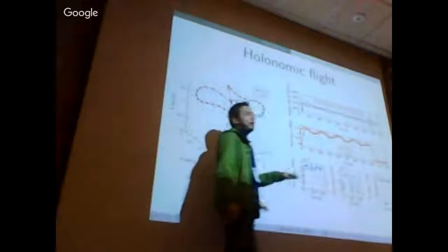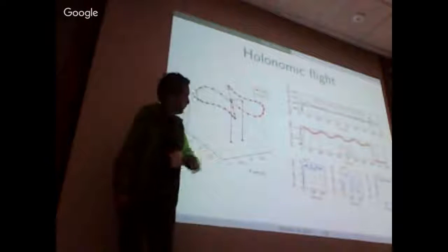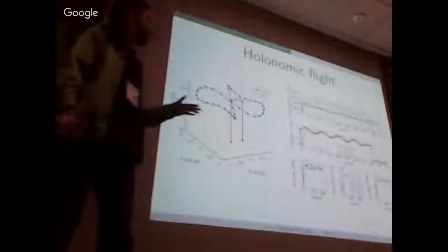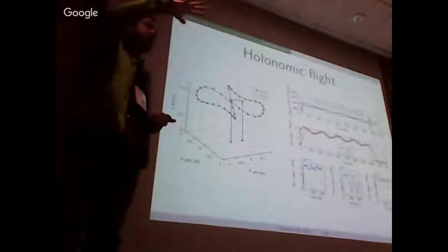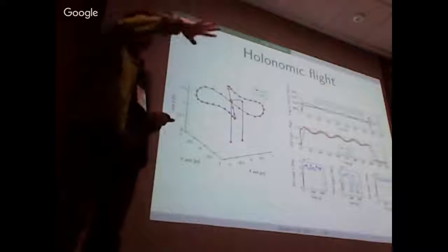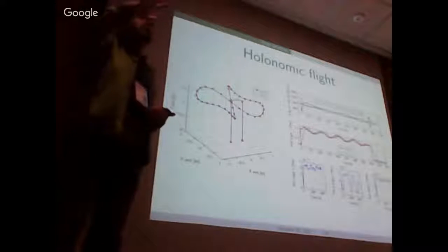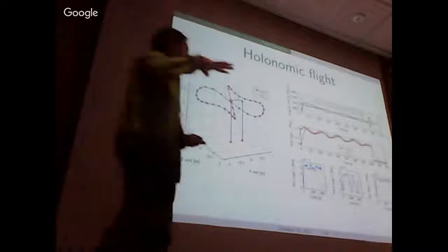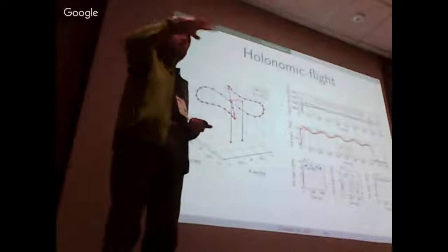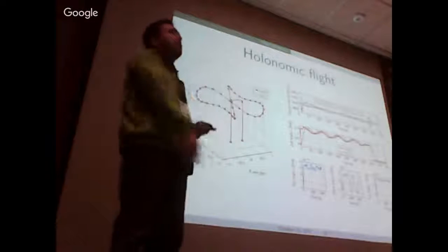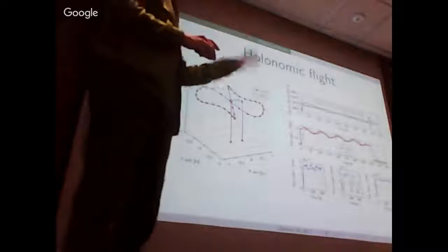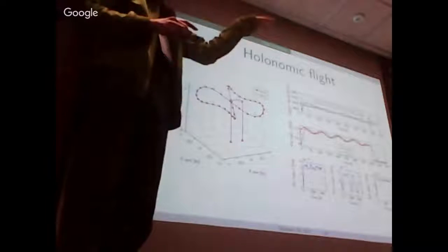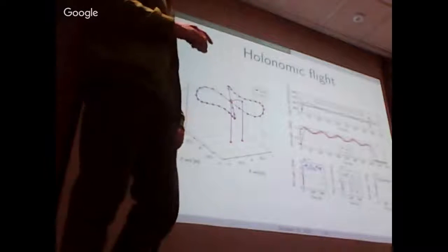And here I show you the Euler angles for the roll and pitch angles. As you can see, they are all approximately 0, which means that this robot took off, described the landing escape, and landed without leaning to one side. It always remained perfectly level. It remained horizontal and perpendicular to the ground, to the XY plane. And the same happens for the yaw angle. It always remains pointing in the direction it started.